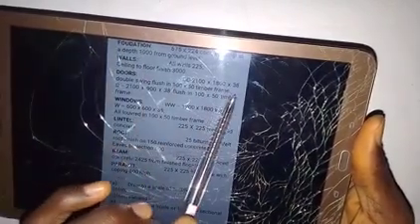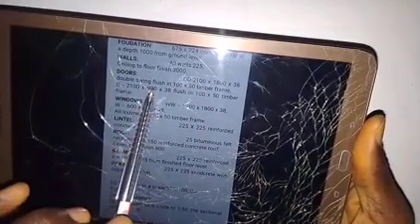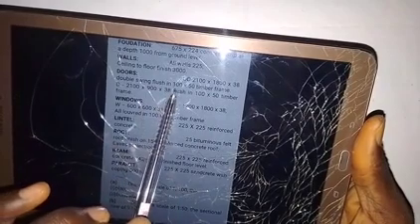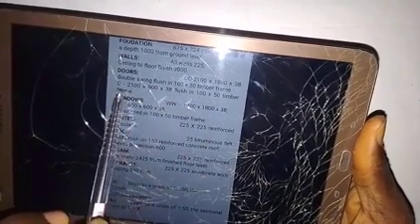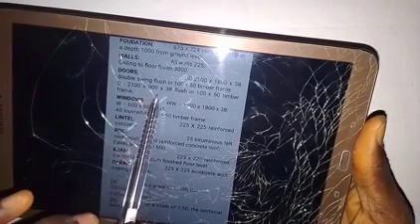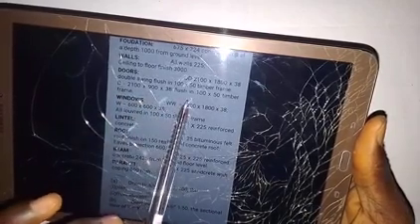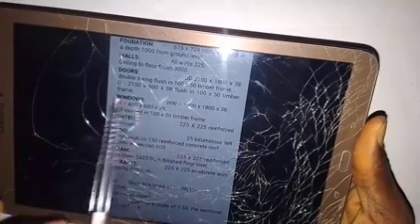Here we have DD 2100 by 1800 by 38 double swing flush in 100 by 50 timber frame. Then we have D 2100 by 900 by 38, also flush in 100 by 50 timber frame.